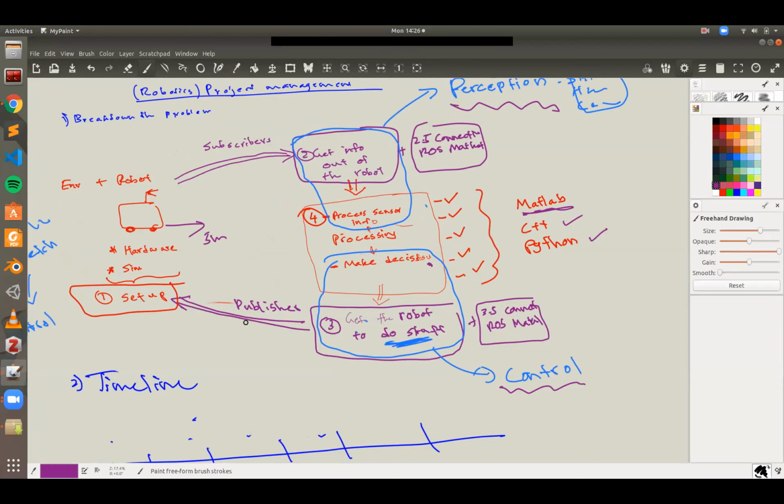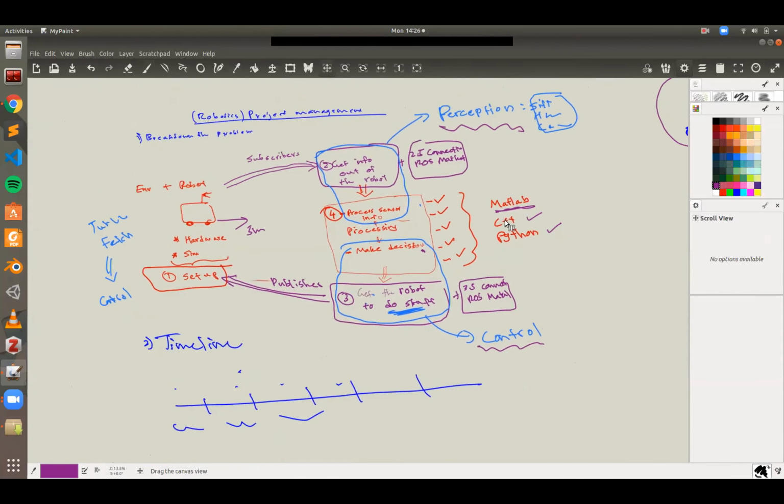In that case, you can't use a ROS bag, but up until this decision-making part, you can use a ROS bag, which will make debugging your code very easy. But when you're actually publishing information back, you need your simulation because you want to inflict change on the simulation. All right, so I hope that answers your question.